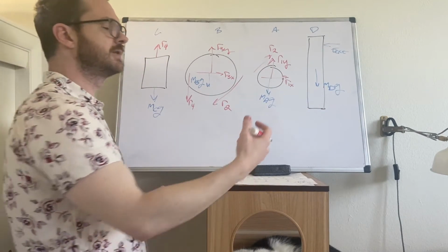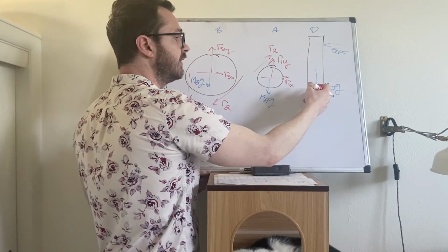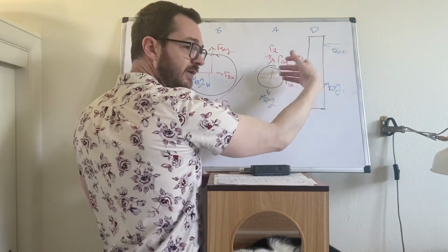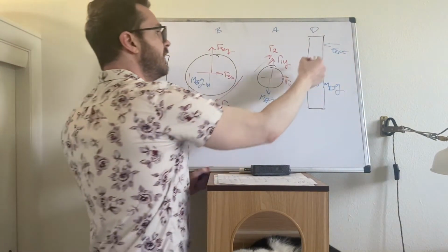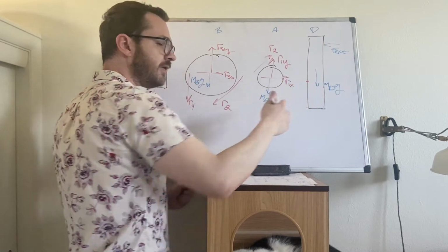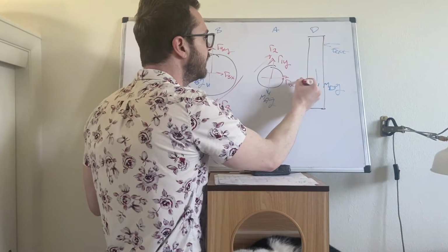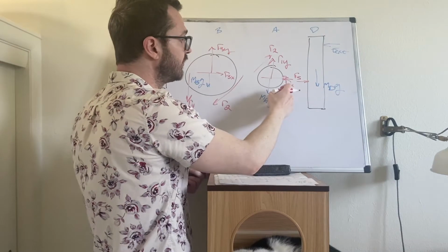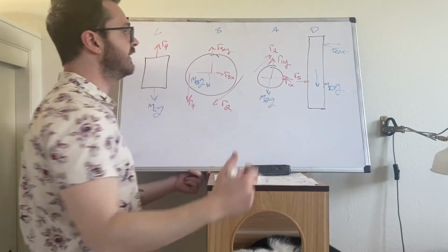Also later, it will make it easy for the sum of moments equation on this handbrake, because it ensures that gravity creates no moment. And of course, we're assuming that this thing stays in contact, so gravity is going to create no moment there. So this is in contact. That means this point between the two, they're pushing against each other, so there's a normal reaction at that location. I called it R5. And since these two diagrams are close, I'm going to do a single R5. R5 is positive on the handbrake, and I did it as negative on body A.